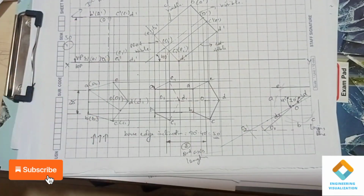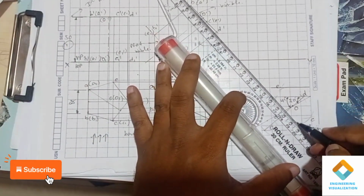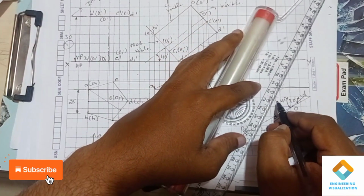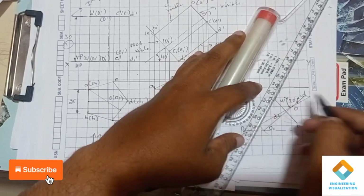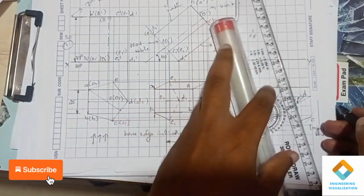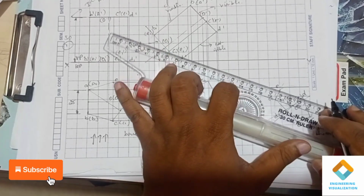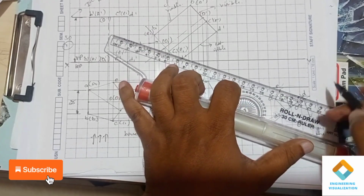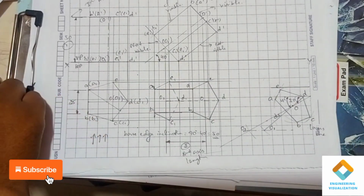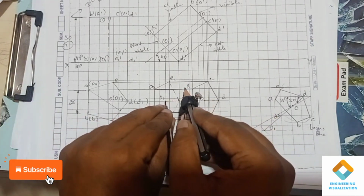Now construct the pentagon. Connect all these points using the scale here. We'll get the pentagon. In the same way we need to do it for the bottom face also. Using O1 and D1 we construct the lower pentagon.